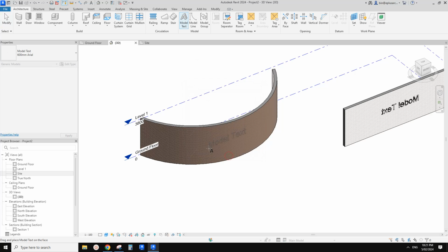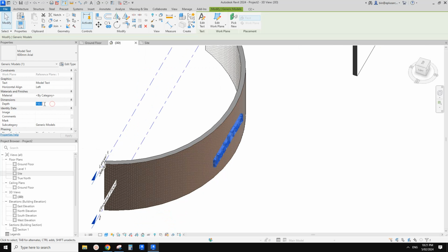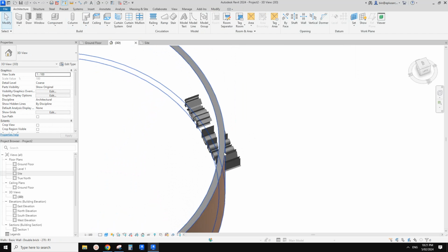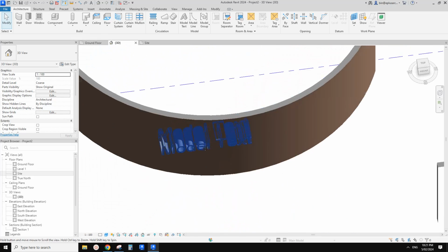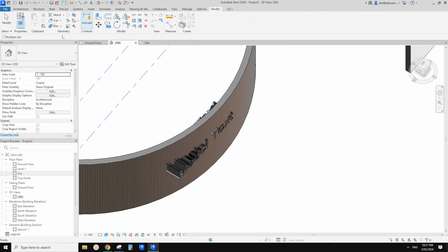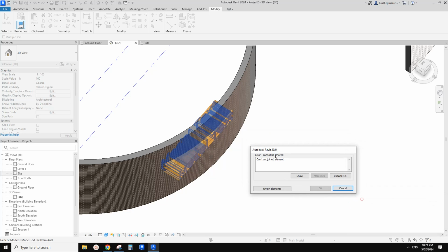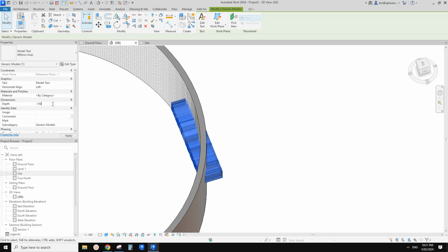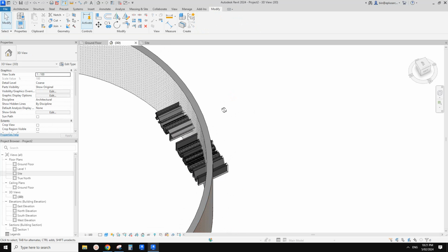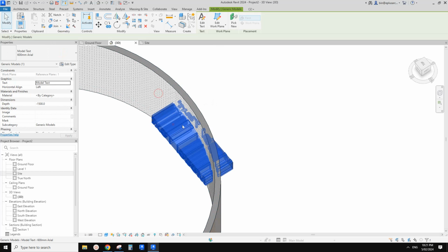and then we can just place a model text onto this. So again, we need to increase the depth or negative, to make sure. Sometimes if this text is not deep enough, it won't work. So let's join geometry. This is what will happen. So just make sure that it's deep enough, and then this should work, right? And then switch join order, hide the text.